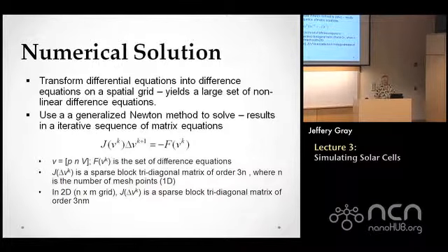And you can go through and do that. And so you'll create a difference equation for every point in the grid. Now, what results is a very large set of nonlinear difference equations. Typically in a 1D simulation, you'll use 250 to 1,000 mesh points. So that means you have 250 times 3, because there are 3 separate equations at each mesh point.